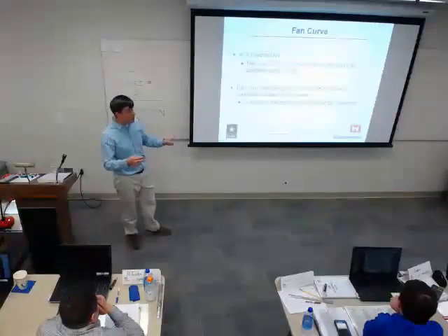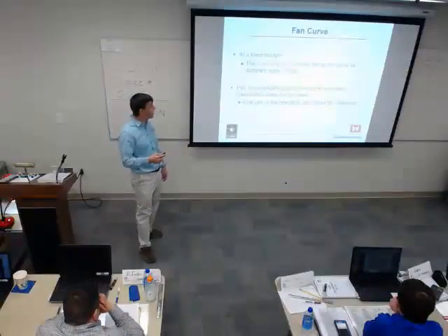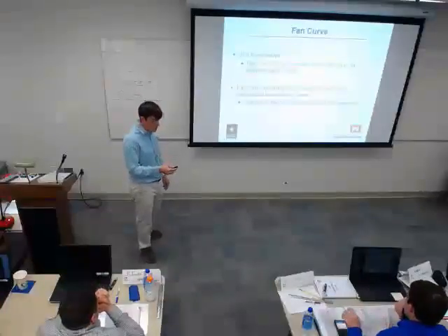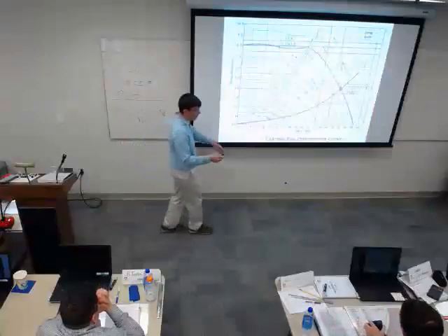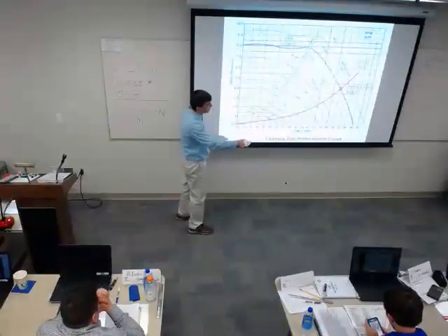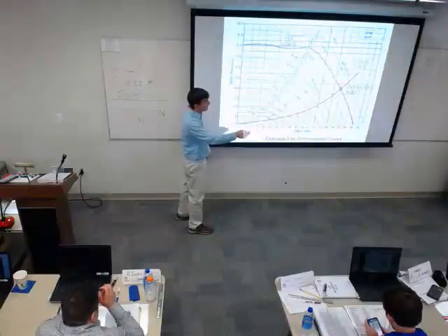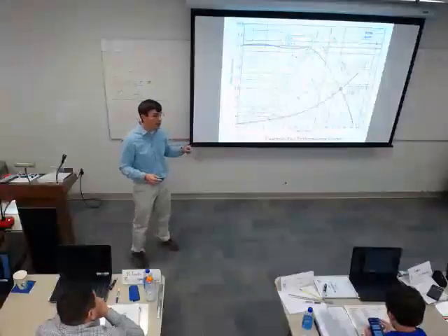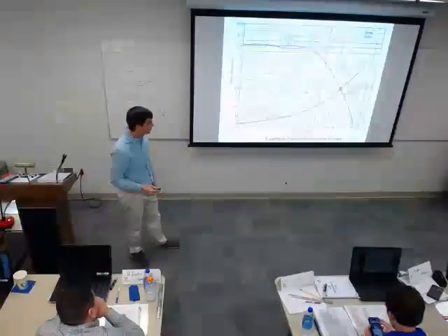This is saying in a different way what I just said. At a fixed fan RPM, the operating point moves along the fan curve as dampers open and close. That's what I just tried to explain: shifting up and down the curve at a fixed fan RPM. So in that example I gave, my fan speed stayed the same, 1,300 RPM, and I rode up and down the fan curve by changing damper positions.